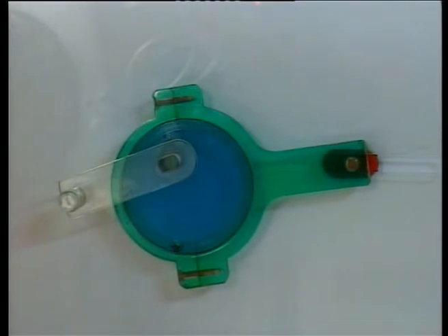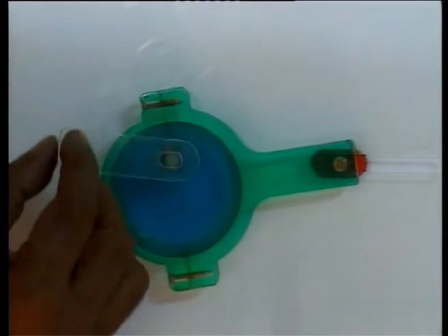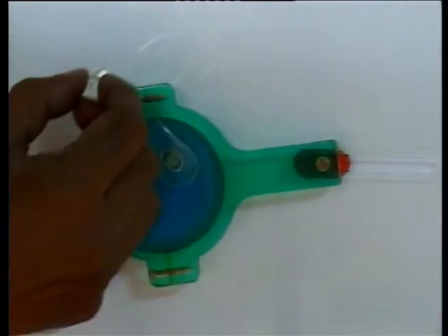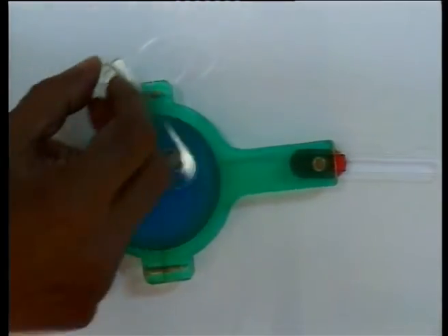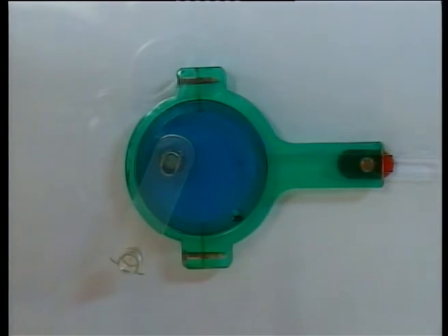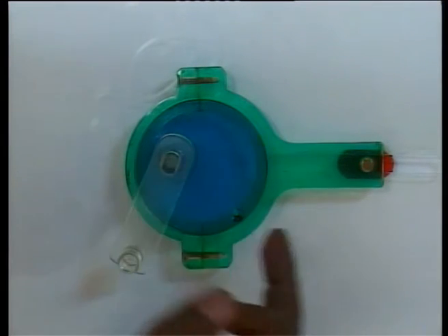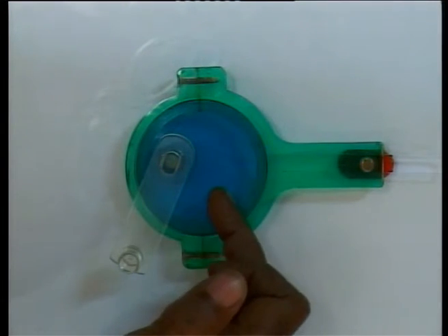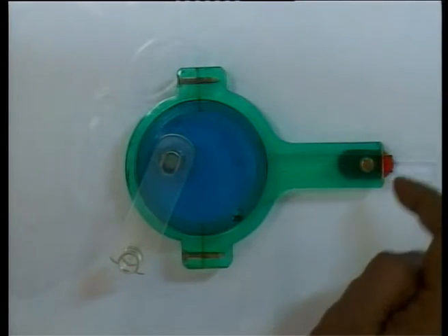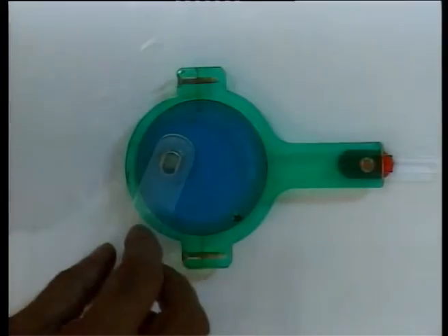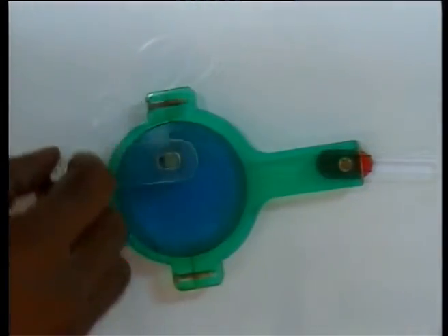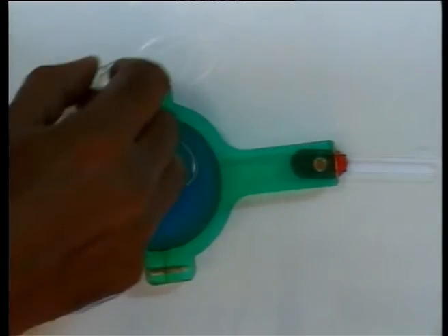Sometimes certain kinematic pairs can be disguised due to certain practical considerations. As an example, let us look at this model of a punching press, driven by this eccentric. Here the eccentric is connected to the motor shaft eccentrically, and this is the connecting rod which is driven by the eccentric, and the punching tool is connected to the connecting rod. The continuous rotation of the motor is converted into to and fro oscillation of the punching tool.